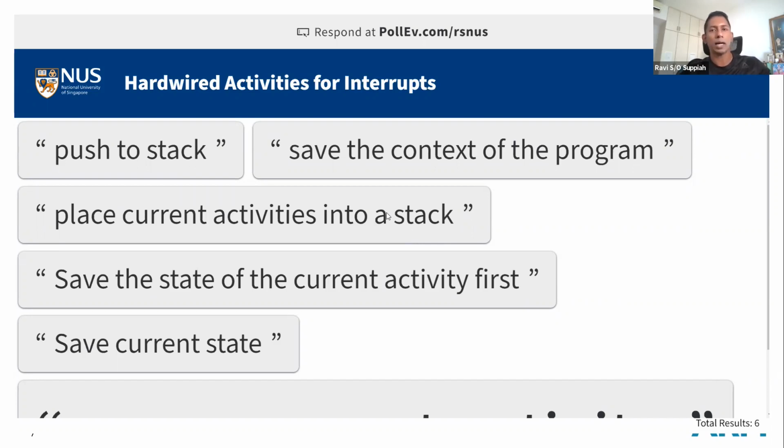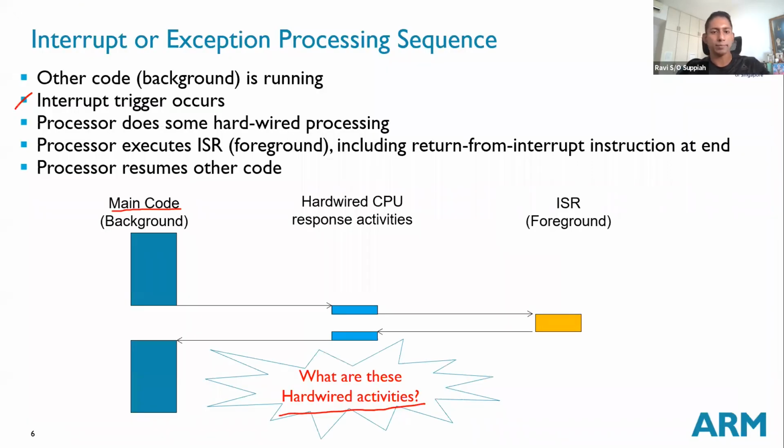We say this is hardwired because you don't have to write any code to do it. It is already handled by the interrupt controller block itself. The hardware does it for us. Everything is in the background, and all we need to focus on is performing the right configuration to detect whatever I need to capture, whether it is a timer overflow, a push button, or a signal coming in on my serial port.